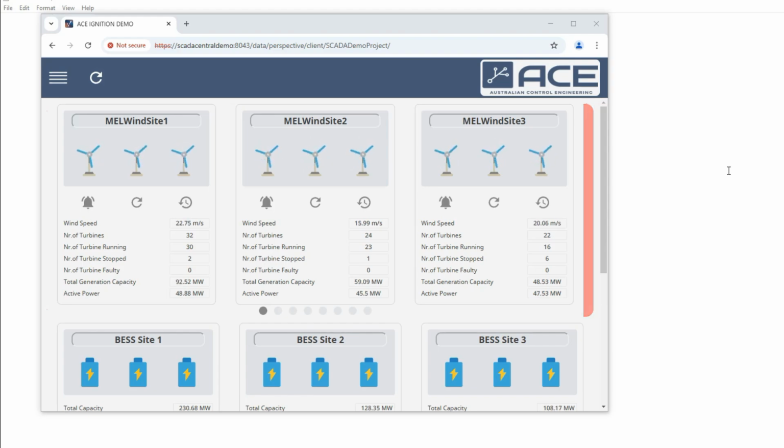With this in mind, we have developed scripts that allow for real-time updates to both wind sites and turbine assets to be sent to the central SCADA's HMI when a new site's MQTT data, using the universal namespace, is known to be received to the central Ignition Gateway's broker.